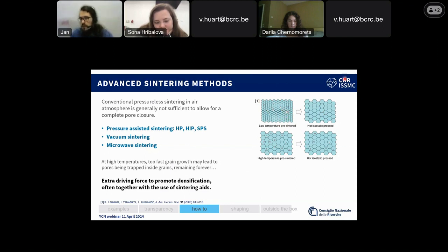And if you play more with the process, like Dr. Ikesue did here, what you can do is not only limiting grain growth, but you can make the material behave more isotropically by introducing a grain boundary phase that actually acts on the single grains.